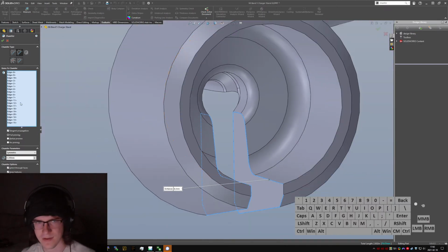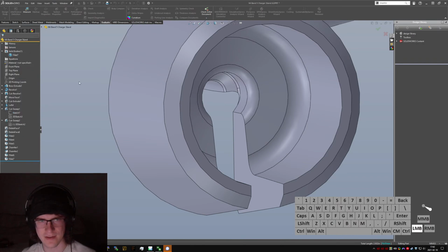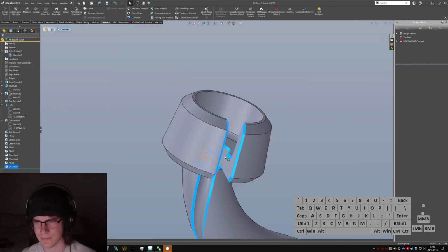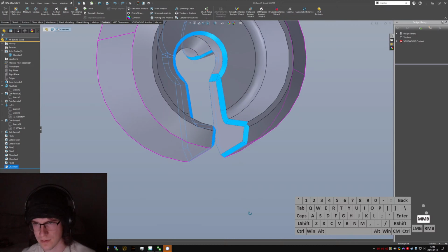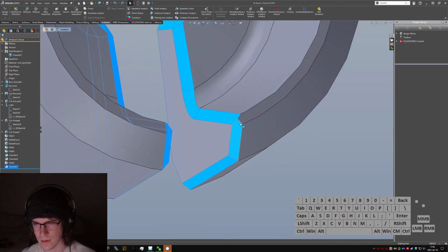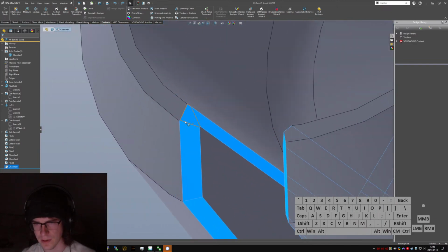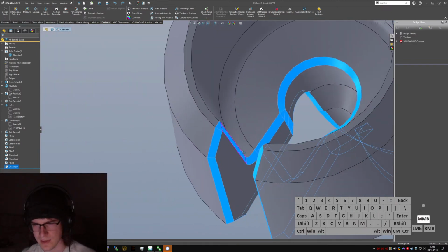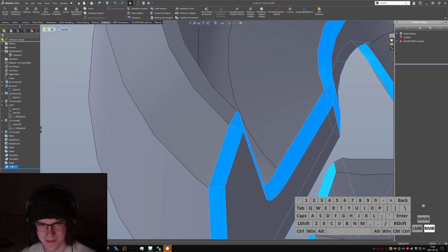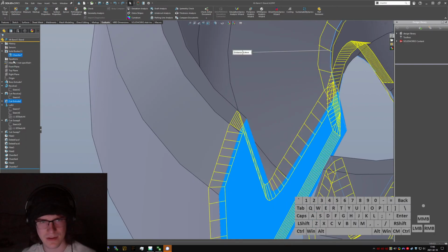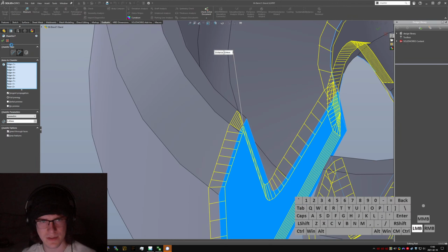What? What is going on? Won't let me generate those chamfers at all. Oh, I don't grab the sliver face. That's what it is. No, I did grab the sliver face. What the hell? Did I make it with an angle or something? No, I did it with an equidistant and a 0.4.